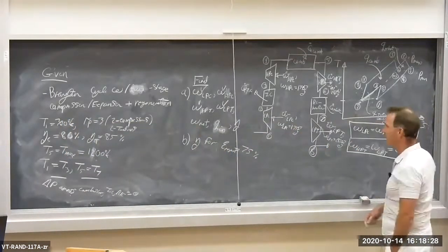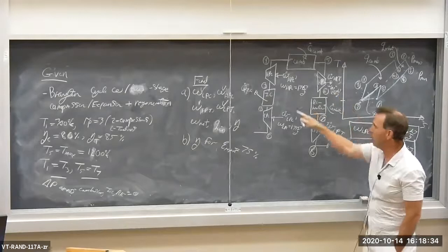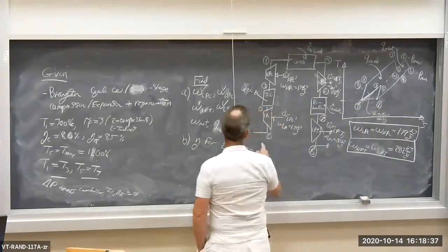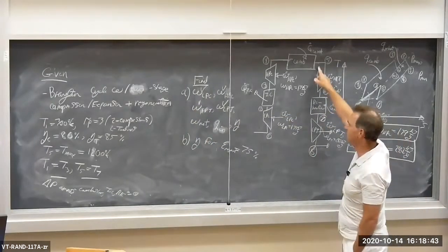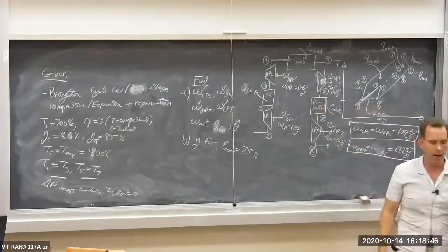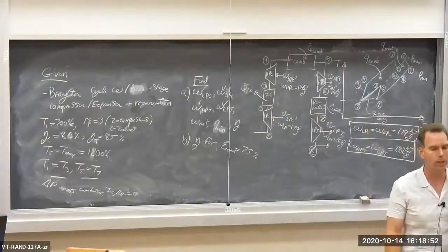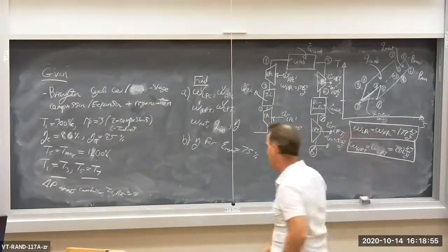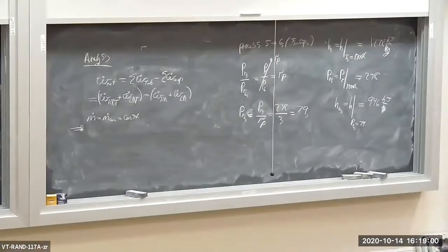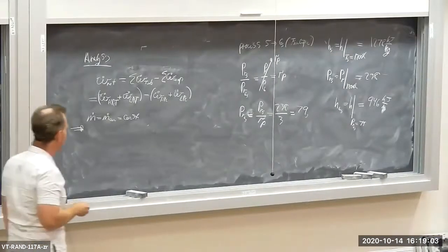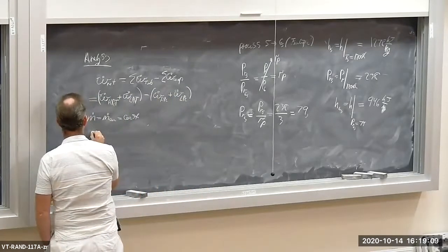So in reality, in a real Brayton cycle, you're actually going to have different mass flows through each part of the device. M dot air through the LPC and the HPC are going to be constant, but as soon as we get to the combustor outlet, m dot is going to be a little bit higher because you've added the fuel flow in the combustor, and then it's going to be higher still when you add the fuel flow in the reheater. We're not interested in that. We're assuming m dot is the same, and in almost all of these problems, m dot is the same for each device.